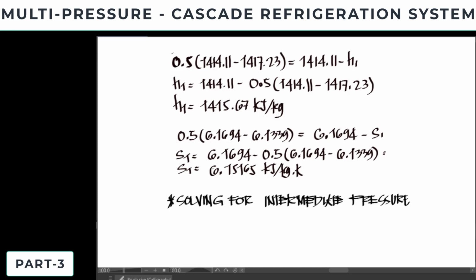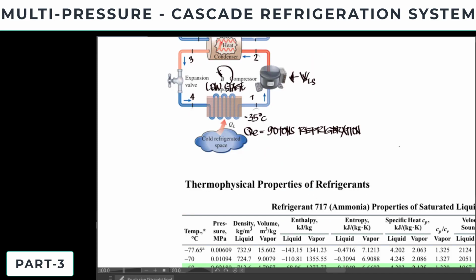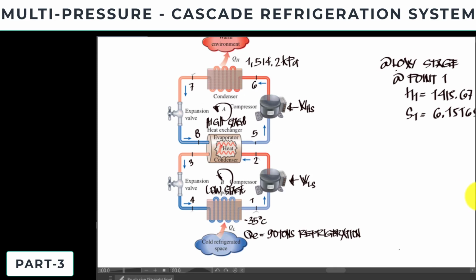And in order to get the intermediate pressure, we need to compute the square root of the high pressure and low pressure sides. So my intermediate pressure will be equal to the square root of the high pressure times the low pressure. Referring here, we have the pressure of 0.1 and 0.6.